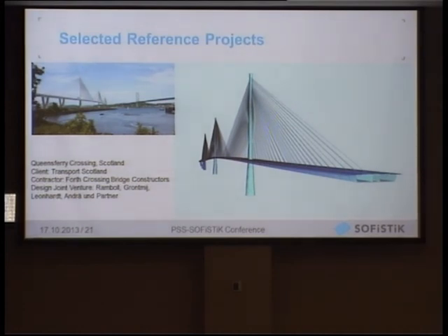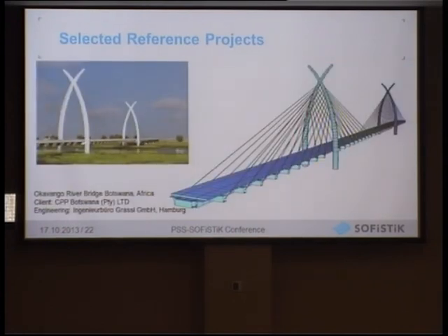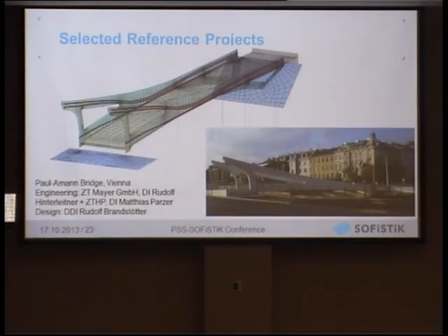I just know three pylon cable-stayed bridges. One is Ting Kau in Hong Kong, and this one, very interesting, because if you know that two pylons are fine with the stiffness, the third pylon is a big problem. So Ting Kau in Hong Kong has these additional famous long cables, which look not so nice because we have this sag due to the length. And here we have this overlapping of cables, which is very characteristic. Another bridge project by Grassl, something for shell design, with some shell pre-stressing, a very nice project in Vienna.